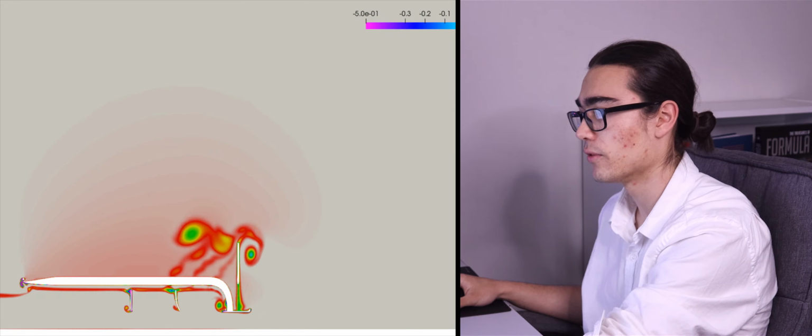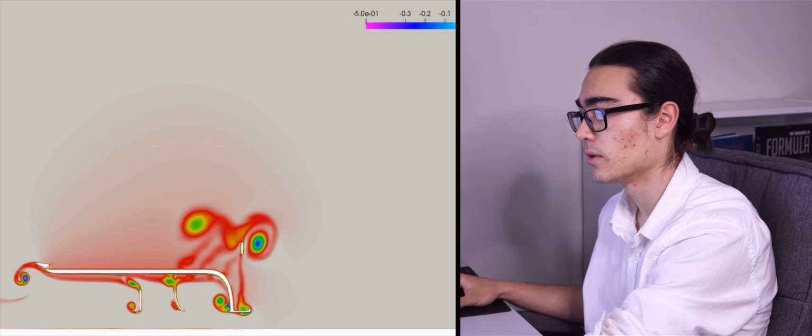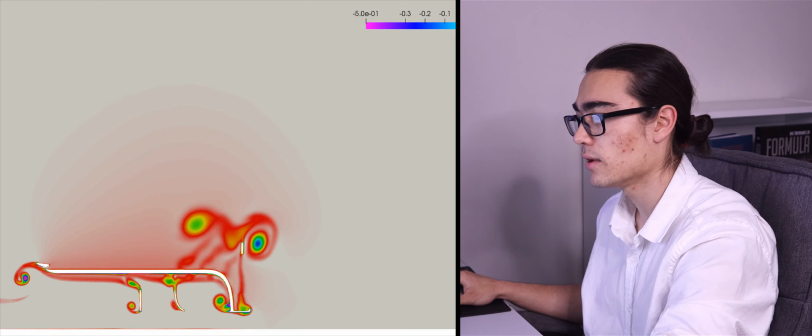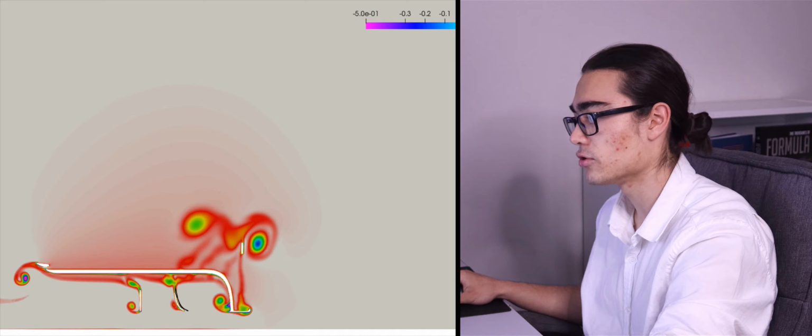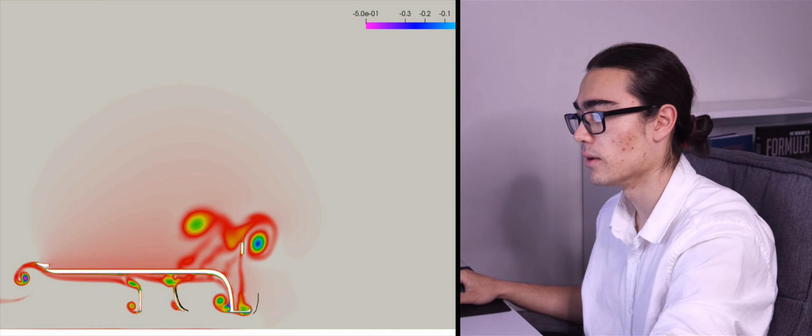So as we move through, you can see that this strake, this supporting strake, the outboard fence here, I do have quite a bit of curvature to it, because naturally the flow is going to want to come under and it's looping around something like this.